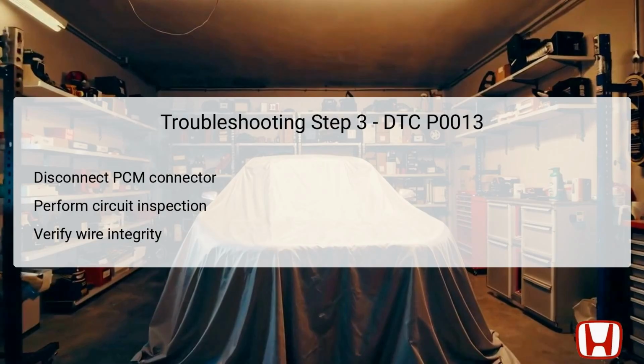The PCM, or Powertrain Control Module, monitors and manages various engine functions, including the VTC system. Before testing, it's critical to first jump the SCS, which is the SRS service connector, using the HDS and allowing a minute for stabilization. This ensures the PCM is in a proper state for testing.